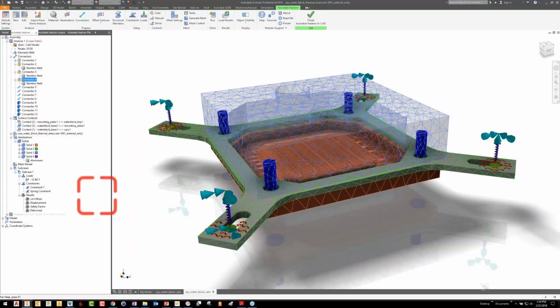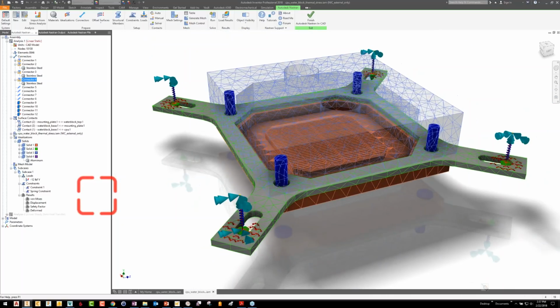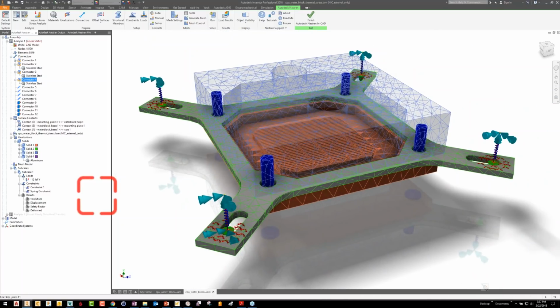So you can see this default mesh, how much coarser that is. I do want to adjust that now, now that we're nailing down this problem and getting more advanced with it. But first, let's bring in our thermal load. What I want to do here is have a couple different subcases, is what they call them, down here in the model tree where the load actually exists. It's actually under subcase 1. We only have one subcase now, but a subcase is a different combination of loads and constraints that you can explore within the same analysis.